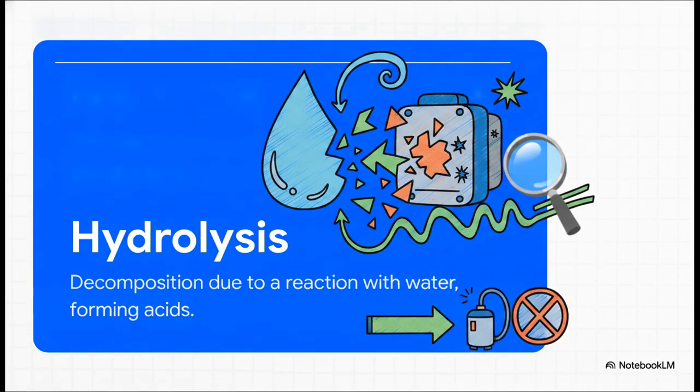And that moisture leads us directly to our most dangerous term, hydrolysis. This is a chemical decomposition caused by a reaction with water. So the really crucial takeaway here is that when certain synthetic oils absorb water, they literally break down into harmful acids and alcohol. And guys, once hydrolysis occurs, it is a one-way street. You absolutely cannot reverse this chemical reaction by throwing on line dryers or just pulling a deeper vacuum. That acid is going to eat the system from the inside out.